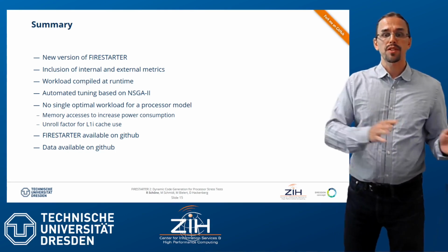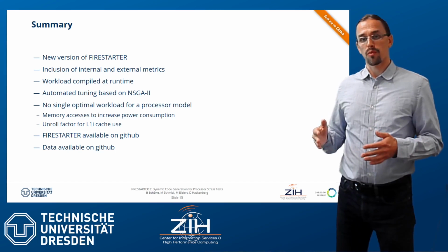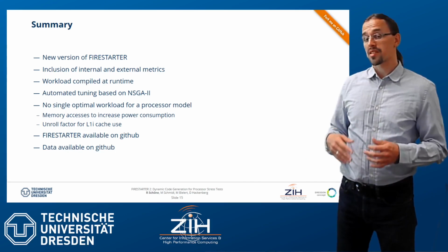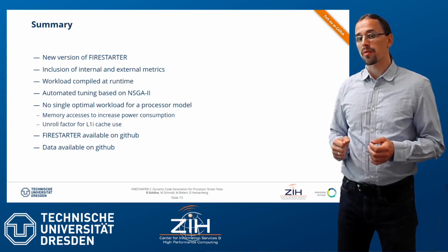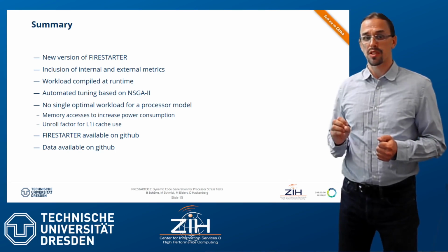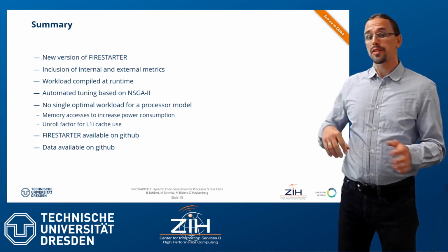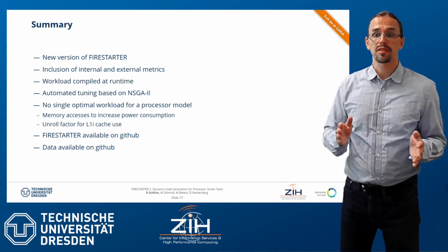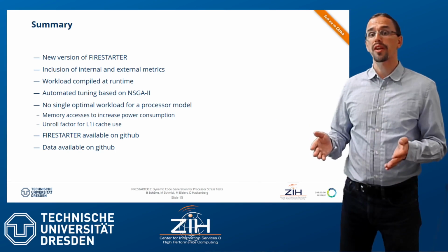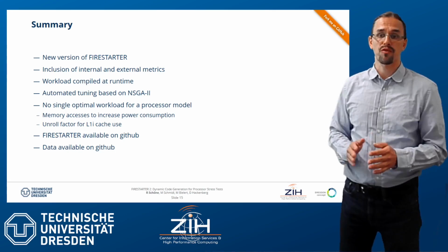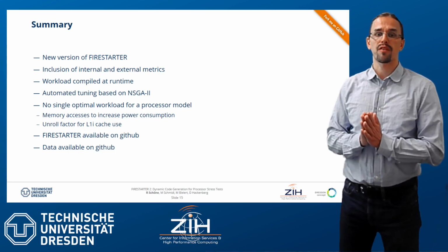And we've shown that there is no single optimal workload for a processor model. It's highly SKU specific, and it's probably not only SKU specific, but also specific for a specific processor. And you can, with FIRESTARTER 2, provide the perfect benchmark stress test for that processor that you have.